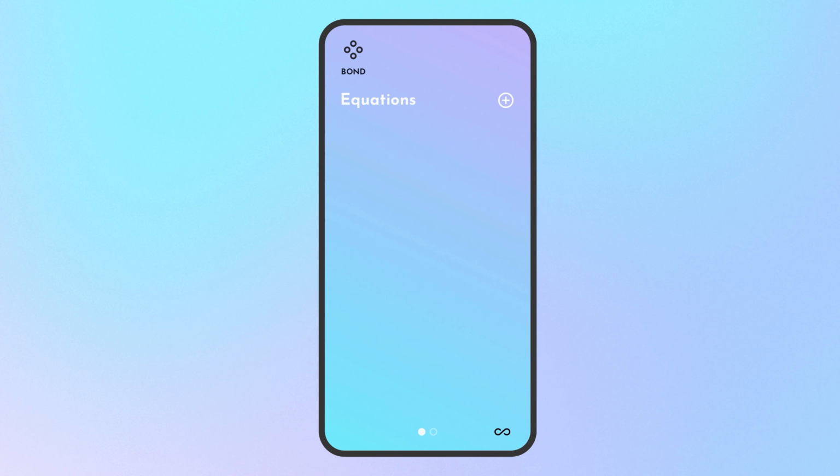Now that we see what the pattern will look like and the distance we will be measuring, we're going to create an equation that sets the distance to the dot's position on the pixel strip. Create a new equation by tapping the New Equation button from the equation's homepage. Since we will always be running this interaction, we're not going to use a when statement. If we did want the LEDs to turn off or go dim when something is no longer in range of the distance sensor, we could add a when in that situation.